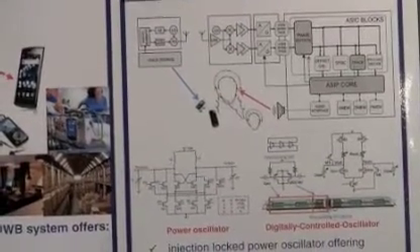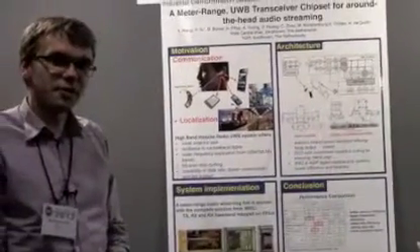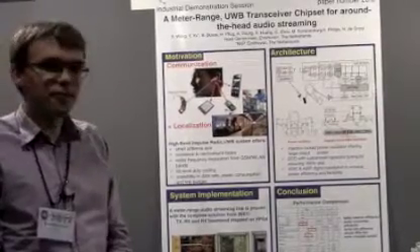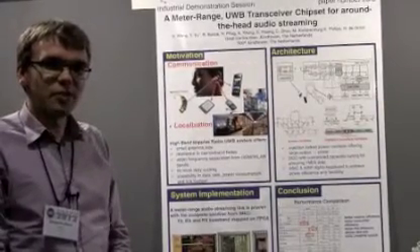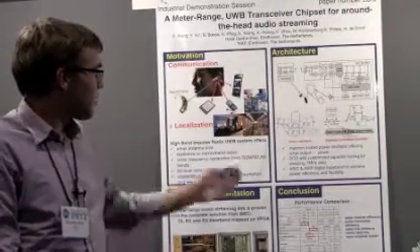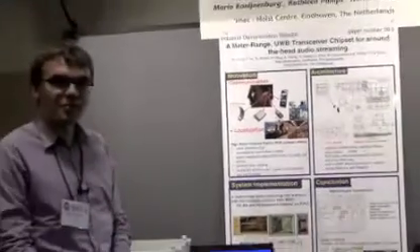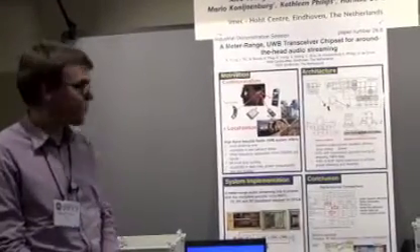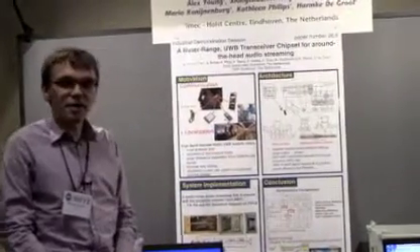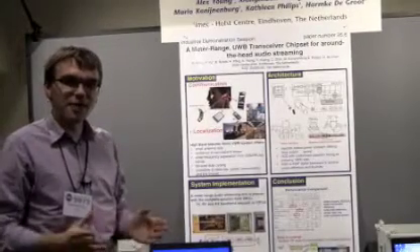What are the highlights of our architecture? For the transmitter, we have an injection-locked power amplifier, which is capable of transmitting an output power of -3 dBm. We have a DCO, which we can tune with steps of 1 megahertz. And on the receiver side we have an ASIC in combination with an ASIP. So this makes it very flexible for us.